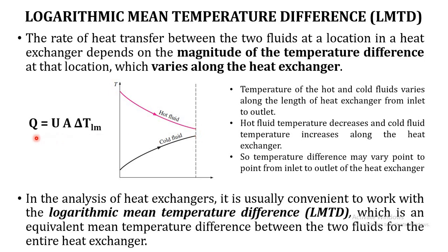So we should consider an average or mean temperature difference here. That is called the logarithmic mean temperature difference. The magnitude of the temperature difference will vary along the length of the heat exchanger.